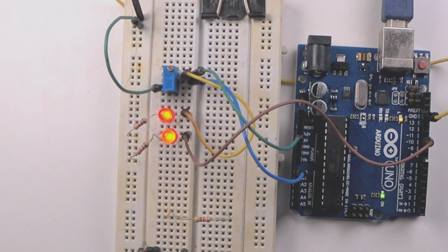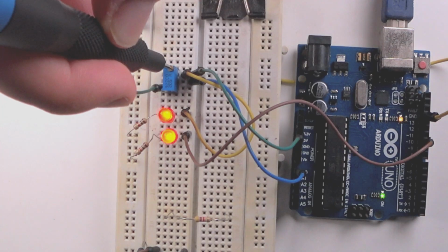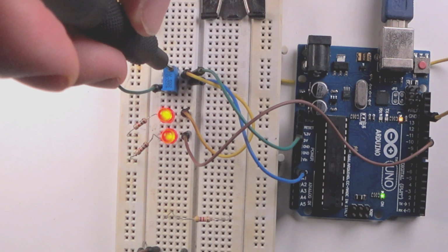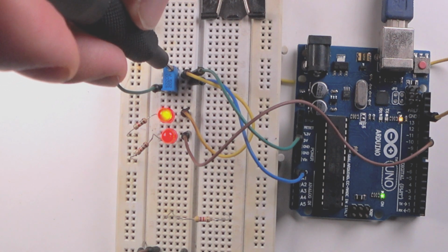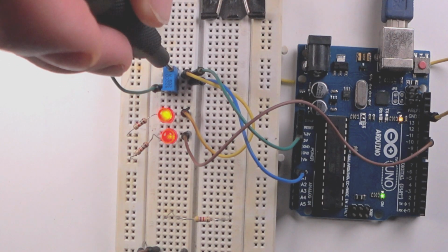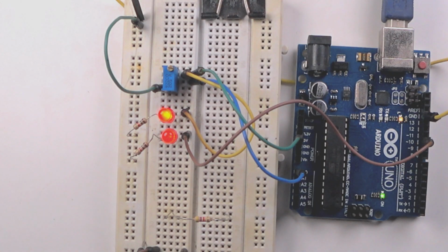Another experiment. In this experiment, the circuit is exactly the same compared to the experiment that we had earlier. What I changed is the program running on this ATmega. Instead of configuring the period using the trimmer, I can now configure the duty cycle. And if I change the duty cycle to a longer off period, you can see that the brightness of the LED reduces. So you can turn it on and turn it off, or leave it somewhere in the middle.